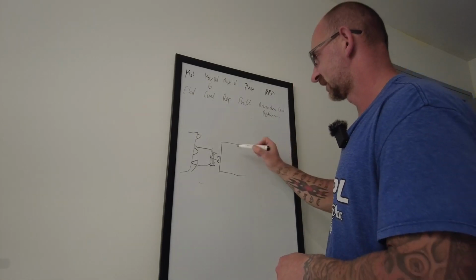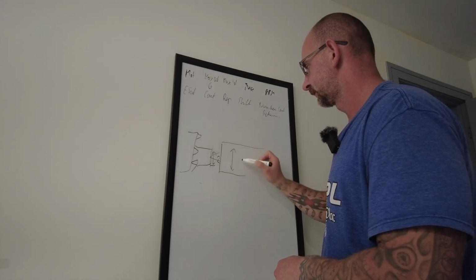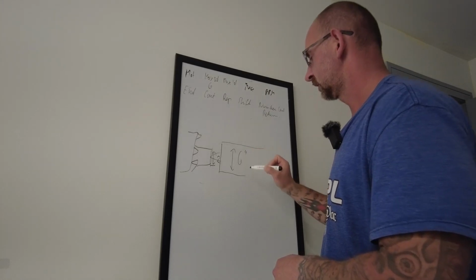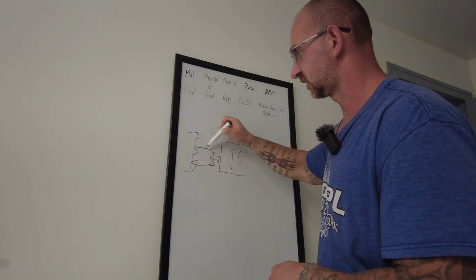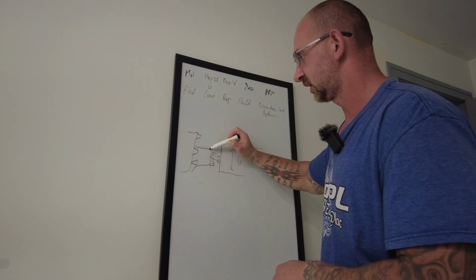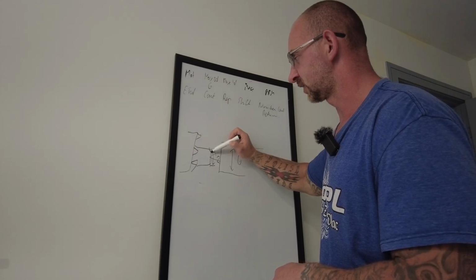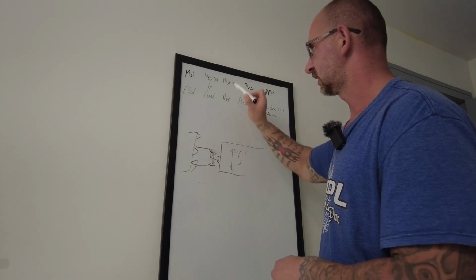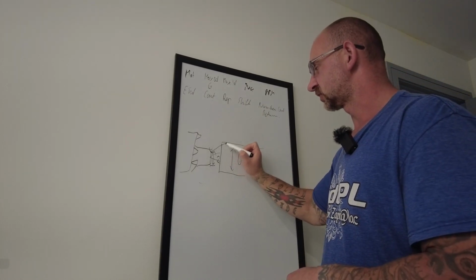Let's say your tailstock is 6 inches. Okay, and you're doing OD turning, right? So it OD turns over here, for example, then you come down, and it removes the chamfer, and if your max OD is set too low, it will crash into the tailstock, right?